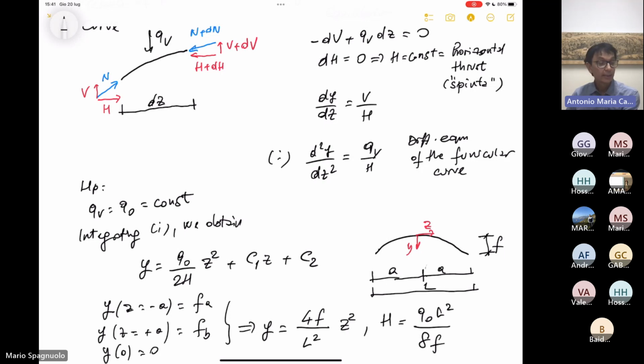in this case, we can neglect the variation, and we can approximate the self-weight with a uniform load per unit horizontal projection. And also in other cases, if this vertical load is not the self-weight but the weight of a filling that covers the arch, this loading condition may have a technical meaning.